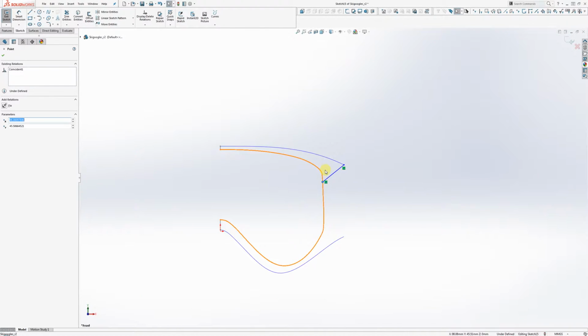And just try to think about the fact that you're going to create a 3D curve later, or an arc later, that's going to go from here to here, and it's going to be one of the two directions for a boundary surface. The way that I'm looking at this area I'm going to fill, I notice this kind of harsh kink in the surface, and that might cause me some nasty geometry. So it seems much smarter for me to bring this up before that kink so that I have a nice clean transition down here and I avoid all of that drama.